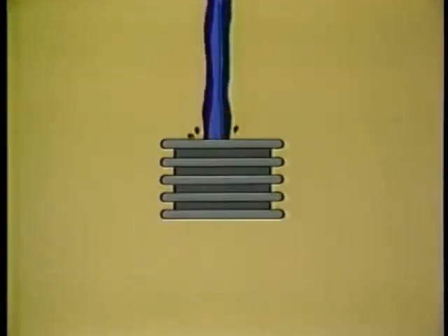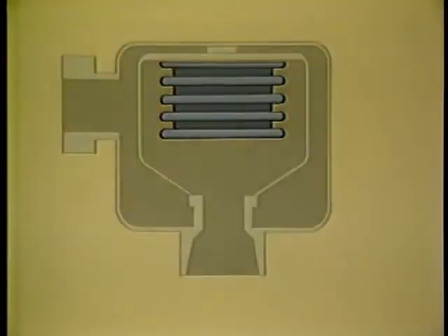Thermostatic traps are opened and closed by temperature changes of the liquids and gases inside them. One type of thermostatic steam trap is the bellows trap, named for the accordion-like cylinder that operates the valve. The bellows contains a liquid charge which vaporizes at or slightly below the boiling point of water.